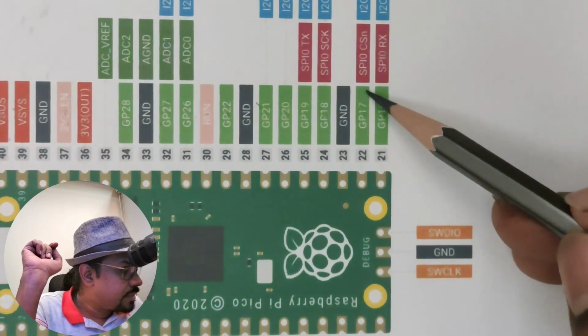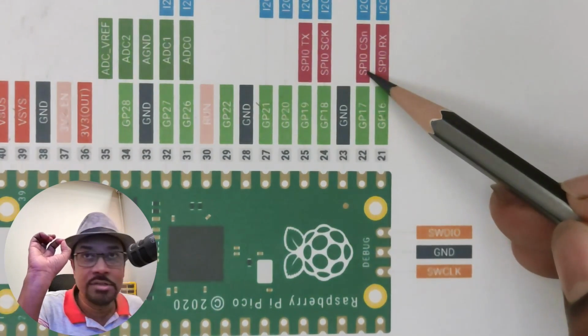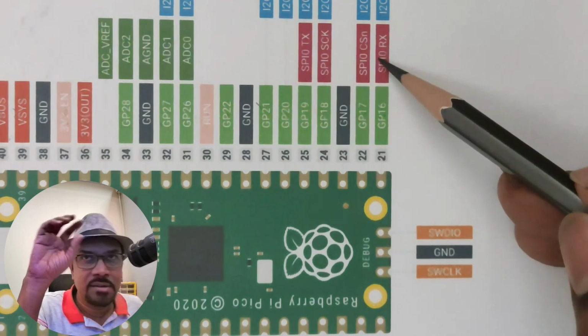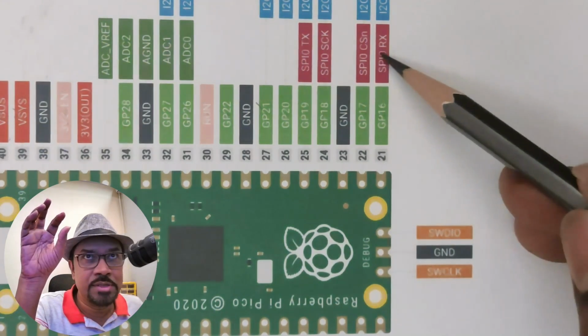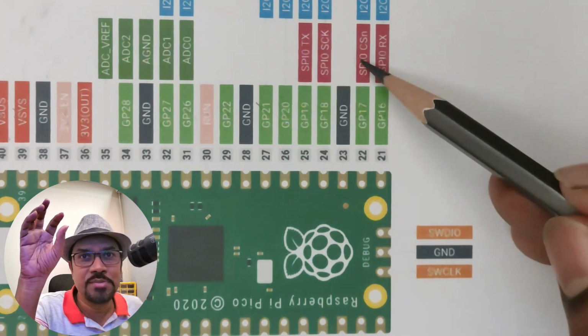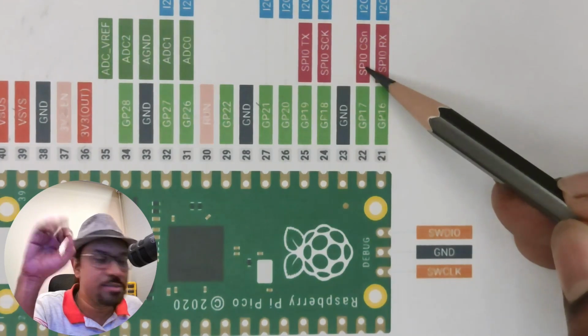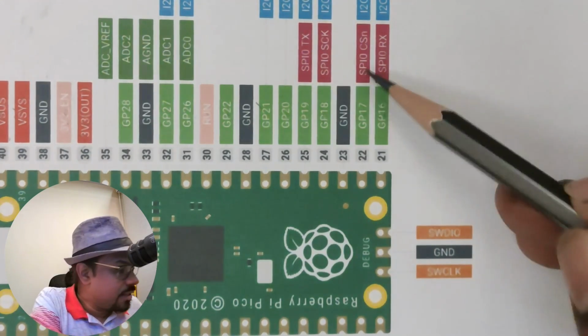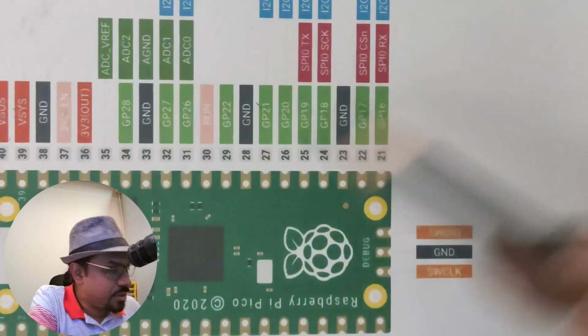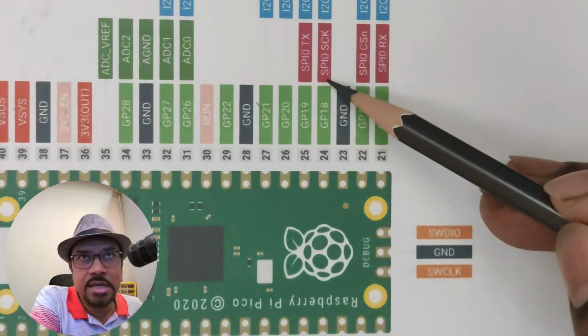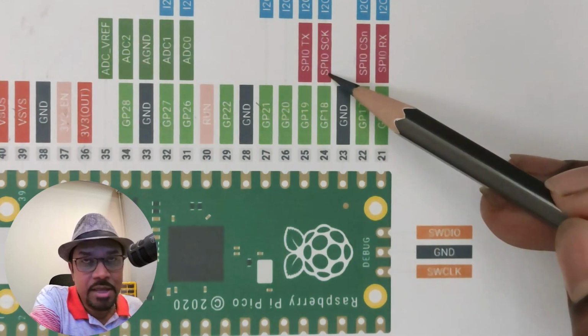And this will be connected to chip select or CS pin. The SPI 0 CSn, right? All of these represent SPI controller 0. You can see it shows up as SPI 0 here, SPI 0 in this place, right? So basically you can see that this is a CS, this will be connected to the CS pin of the display. And I'm not using the ground because I'm using the ground from this side anyways. And you can see that the other pin that is there is an SCK pin. This will be connected to the clock pin, right?